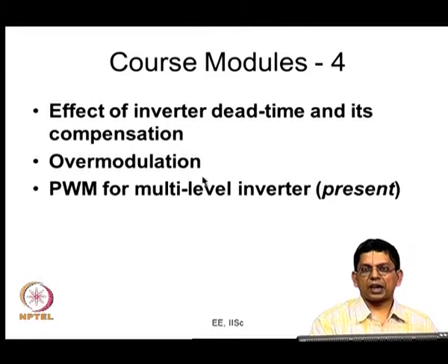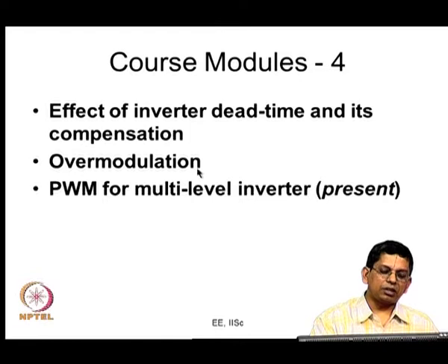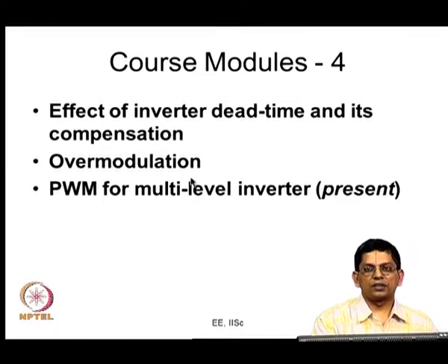The same philosophy can actually be used, with certain modifications, for a 3 level inverter also. For a 2 level inverter, with over modulation you can increase it from 90.7% to 100%, nearly a 10% increase in the voltage, whereas that percentage increase could actually be a little lower with this. And of course, those algorithms that I have mentioned can be expanded. Some of them have been extended, and some can be extended to over modulation of a 3 level inverter. So, if necessary, we can also do that. But we would be focusing on this.